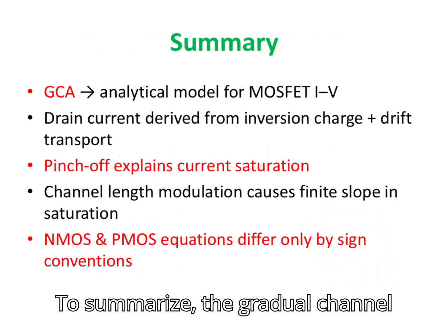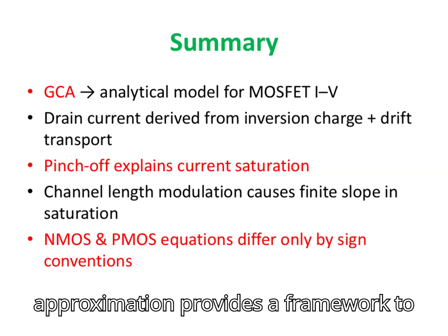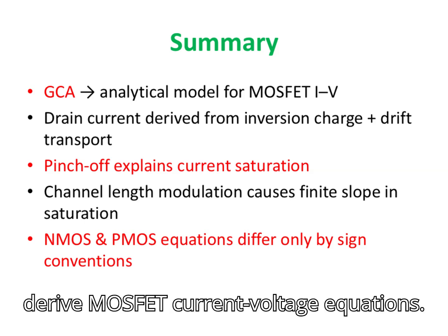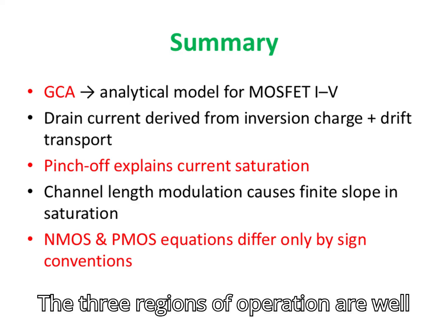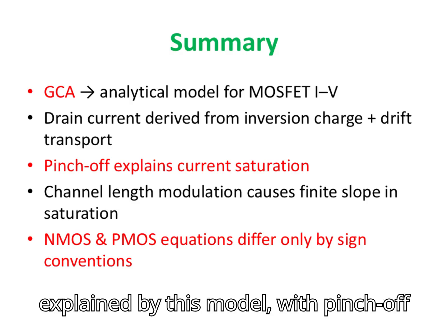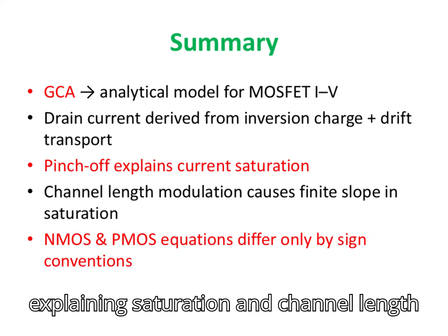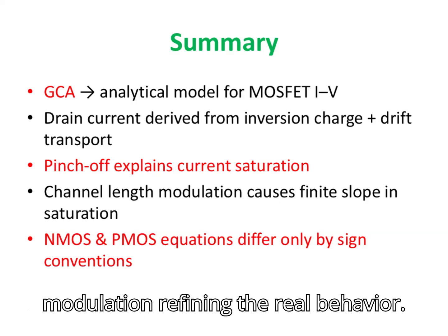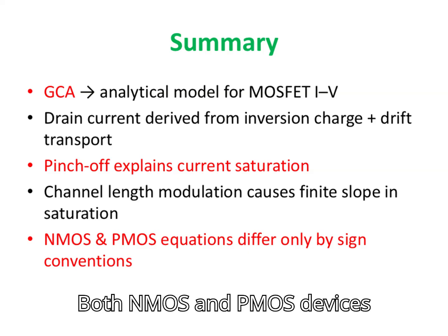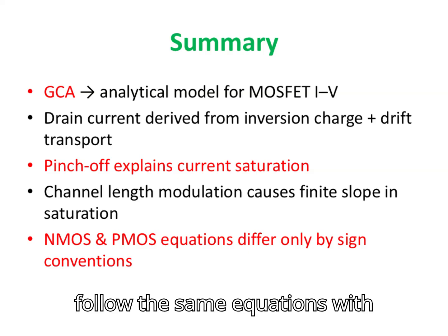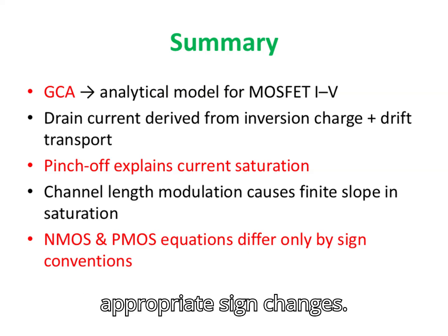To summarize, the gradual channel approximation provides a framework to derive MOSFET current-voltage equations. The three regions of operation are well explained by this model, with pinch-off explaining saturation and channel length modulation refining the real behavior. Both NMOS and PMOS devices follow the same equations with appropriate sign changes.